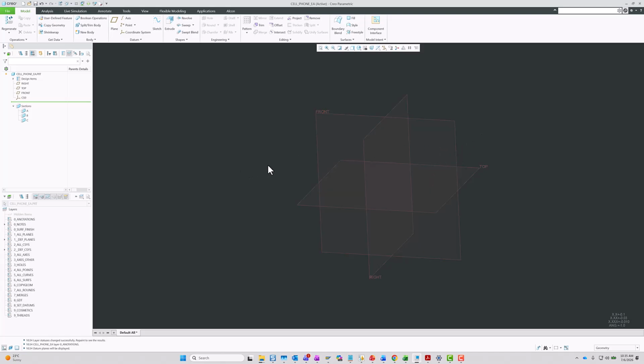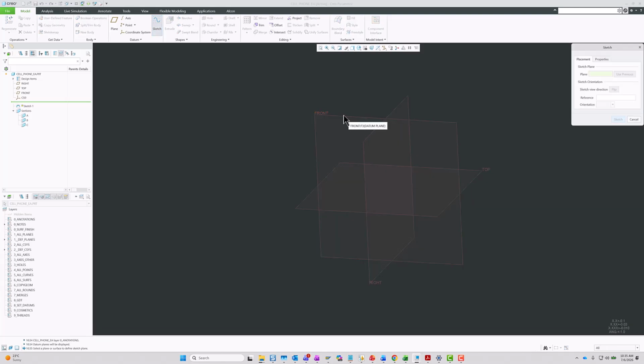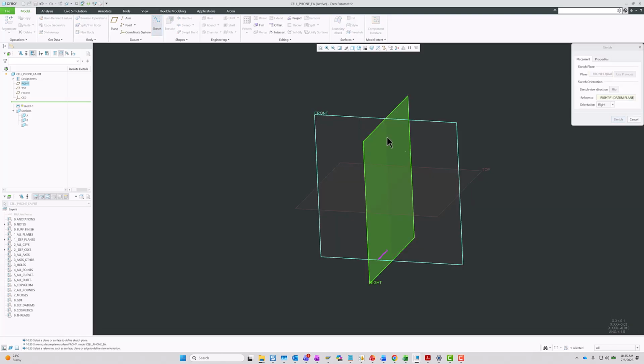All right, the next step is to create the screen. Before creating a 3D model, you need to create a sketch. Based on the 2D sketch, you are going to create a 3D model. You click here on front. You need to tell the software which plane you are going to draw the 2D model on. You may be wondering how to select the correct plane.